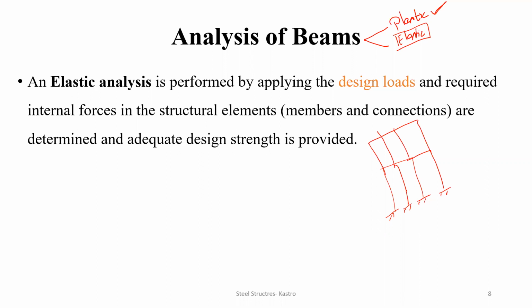And apart from that, you are also going to find out if there are any loads coming in the lateral direction, right? There is an obvious case that sway will happen in the member. This is the entire analysis of a section. You're going to find out the loads and then analyze the member in such a way that you determine whether the member is able to carry a safe amount of loads or not, and also whether the end conditions are safe or not.